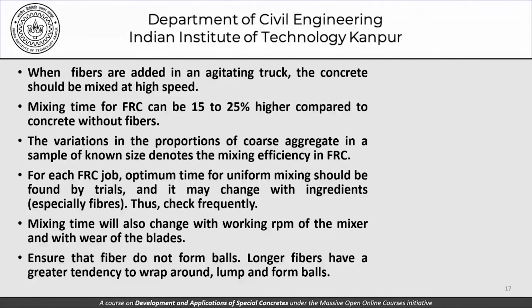Mixing time will also change with the working RPM of the mixer and the wear and tear in the blades. In fact, the wear and tear in the mixer and the blades could be another parameter that we should be careful about when we are trying to use fiber-reinforced concretes, especially steel fiber-reinforced concretes.